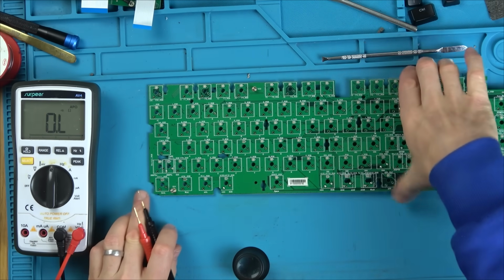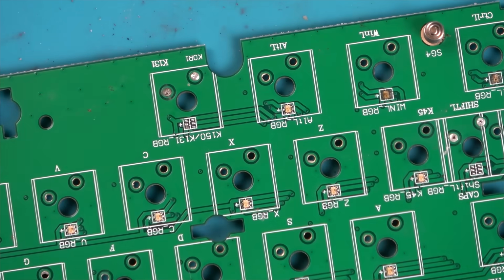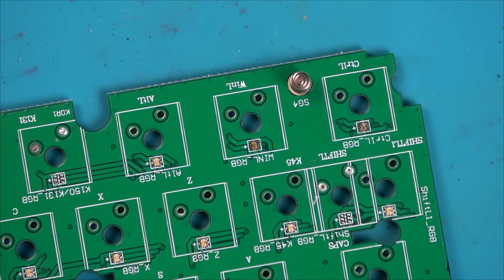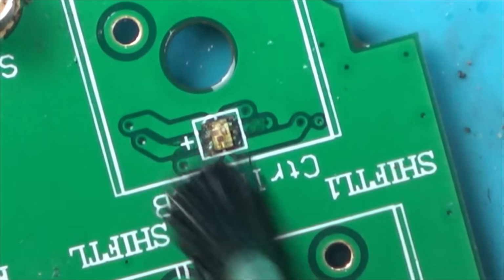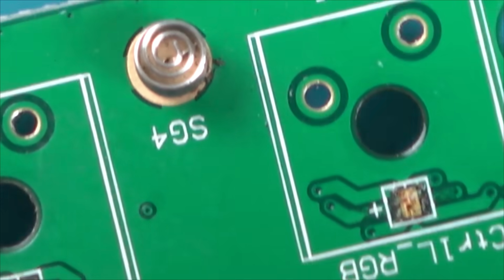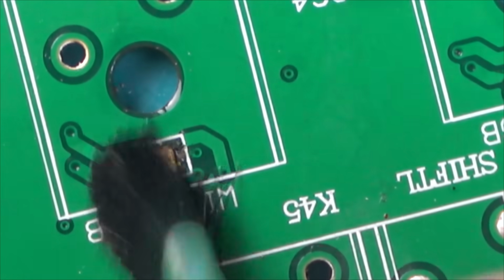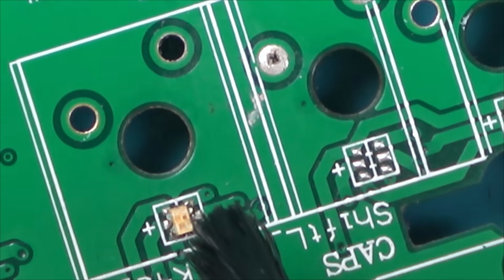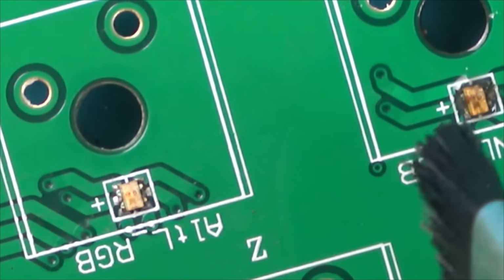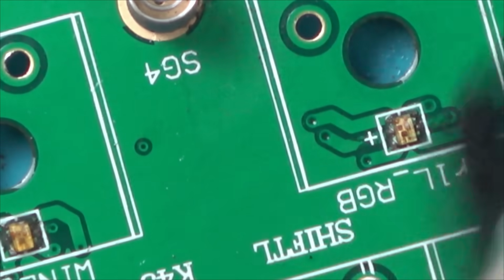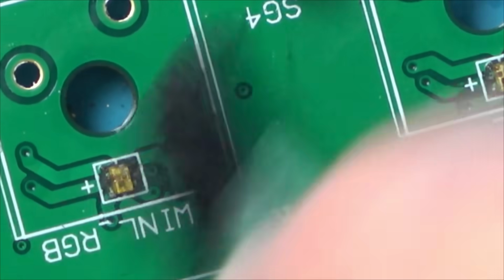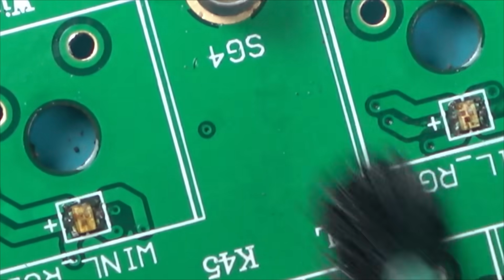Right, it looks a bit crusty down in this corner here. Do you know what, I'm going to put it this way around to make it easier for me. I wonder if those pads broken through there. Yeah, they're definitely corroded, aren't they? Yeah, these ones are okay. So this bottom corner's got it. So maybe, you see, it's not sending a signal through to the rest on that kind of matrix line. That doesn't look good at all, does it? Could this be our problem?